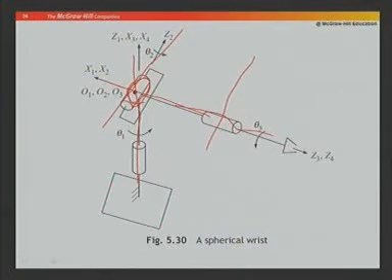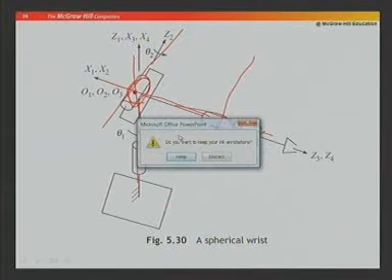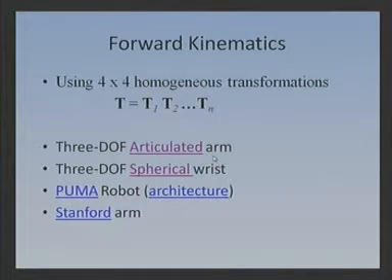So, you have seen the arm here. This is the arm 1, 2, 3, and then I am adding 4, 5 and 6. So, now my hand has a total of 6 degrees of freedom, which will be able to move any object from one place to another place comfortably as per your requirement. And that is the reason in industry we use a hand-like robot for any purpose.